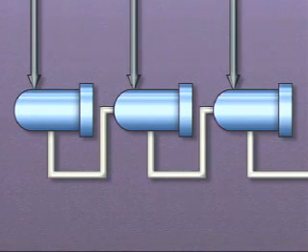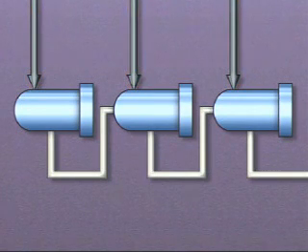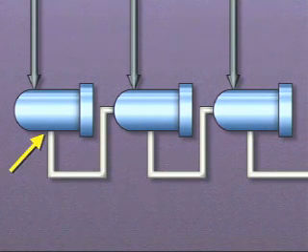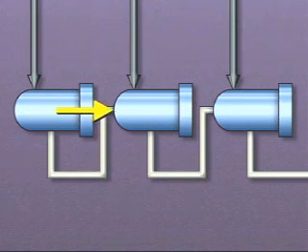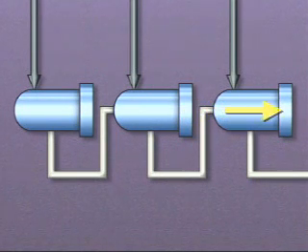Typically, to recover the maximum amount of heat from the extraction steam, a train of heaters uses a cascading drain system. In each heater in the train, drips are subcooled by the transfer of heat to the feedwater in the heater's drain cooler section. This helps keep the drips from flashing to steam in the drain line. The flow of drips moves from the highest pressure heater to the lower pressure heaters.